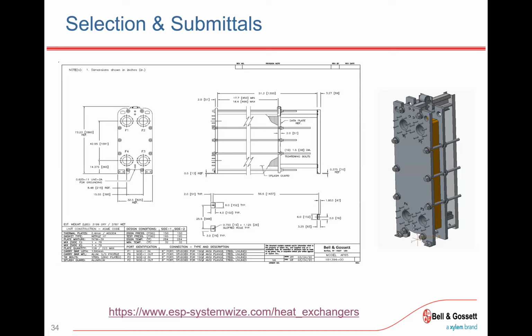Webstone is a line that's primarily valves, and their whole thing to the market is really reducing leak paths. So rather than somebody putting 6 or 7 valves and fittings together with all these different leak paths and sweating everything or threading everything together, they usually have a solution where it's already packaged. Like that big outlet on the wall. So that one's for a temperature sensor.